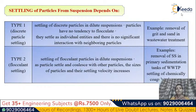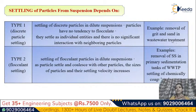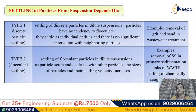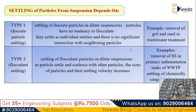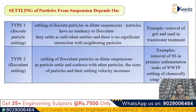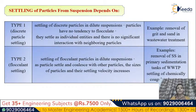Examples of discrete particles are the removal of grit and sand in wastewater treatment. An example of flocculent particles is the removal of suspended solids in the primary sedimentation tank of a wastewater treatment plant, or settling of chemically coagulated wastewater in a sedimentation tank. So discrete particles work under the force of gravity, and flocculent particles work on the mechanism of coagulation and flocculation to change their properties.